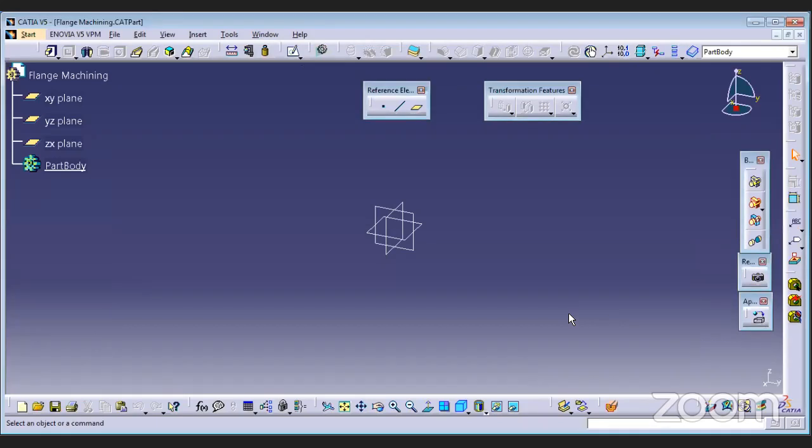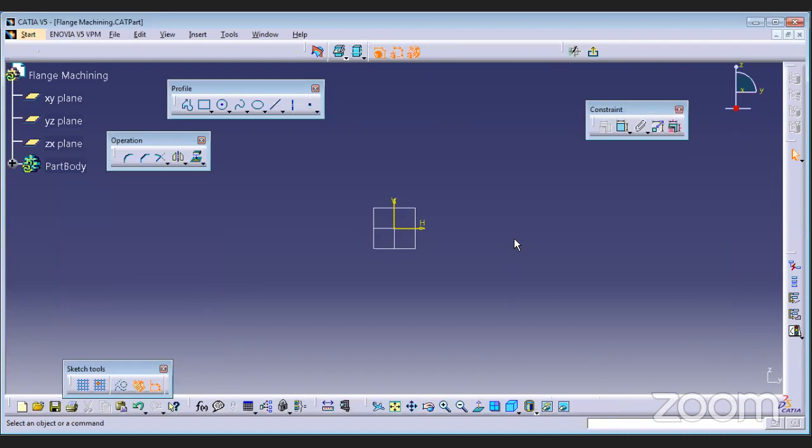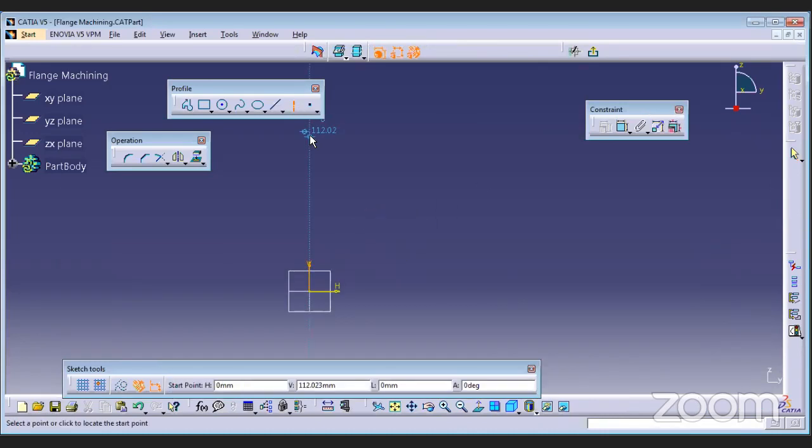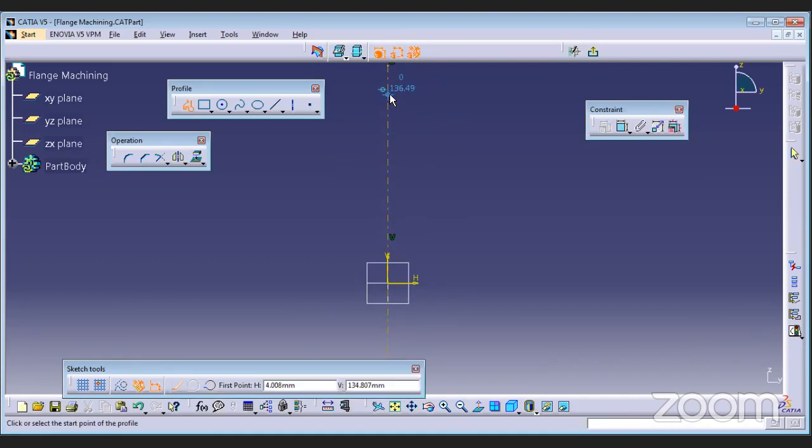We are going to create a machining model. It's a circular component, as you have seen in the image and the drawing. So we start with the sketch. You know how to create a sketch. I'll go to the Sketcher environment. Here I am positioning the sketch on the YZ plane. First I will create an axis because this is a circular component. We are going to use the shaft command. To create circular components, revolve features are used. So this is the shaft command.